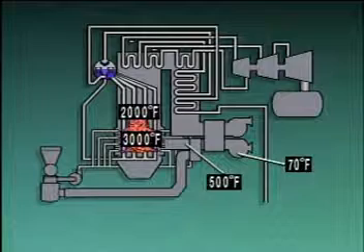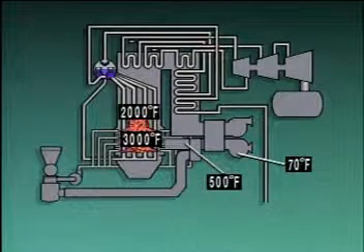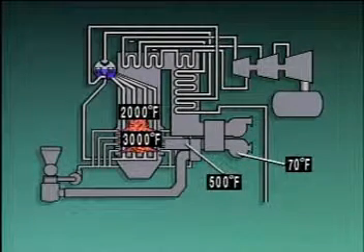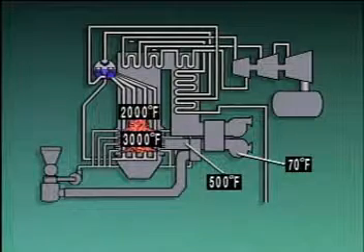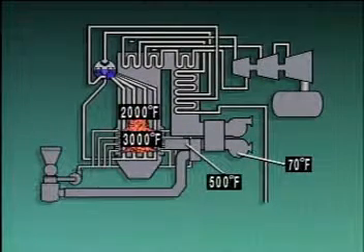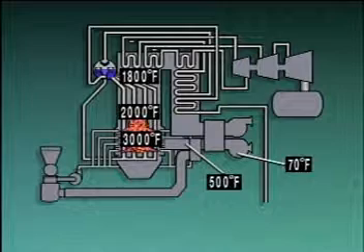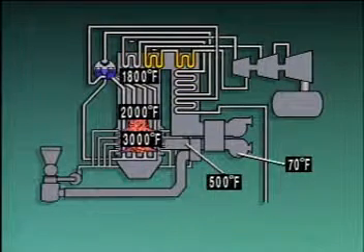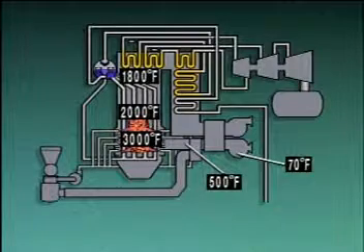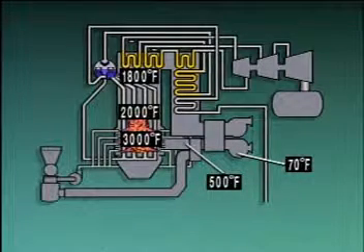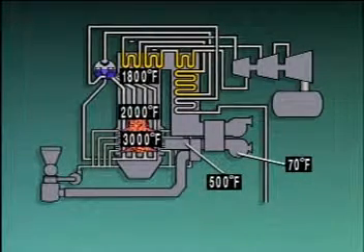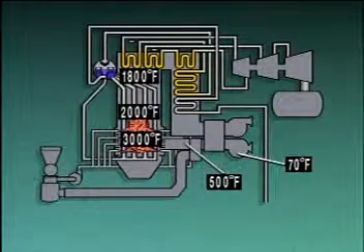By the time the combustion gases enter the area of the gas flow path that contains sections of boiler tubes called superheaters and reheaters, their temperature has dropped to about 1800 degrees Fahrenheit. Superheaters and reheaters are heat exchangers. Their purpose is to raise the temperatures of the steam produced in the boiler so that the steam can do more work. Steam flows through the superheater and reheater tubes.